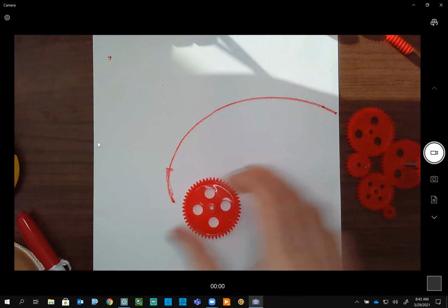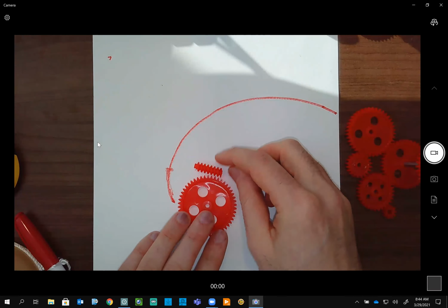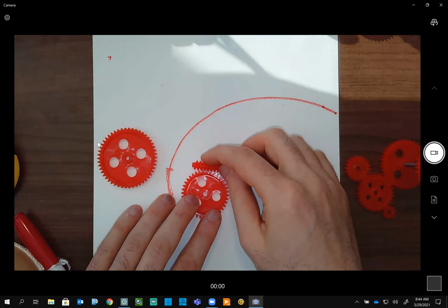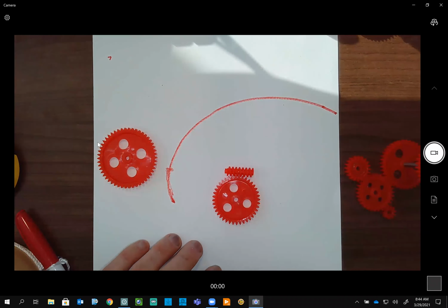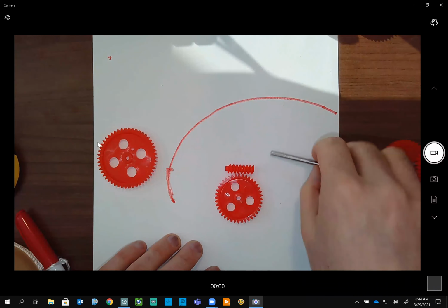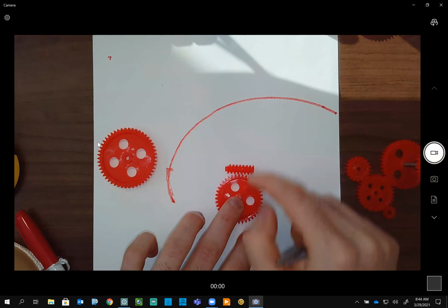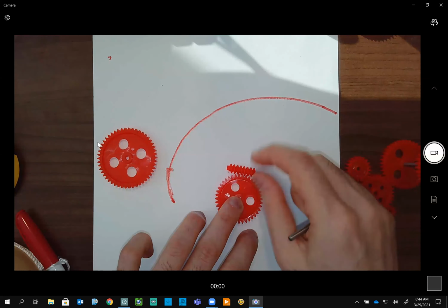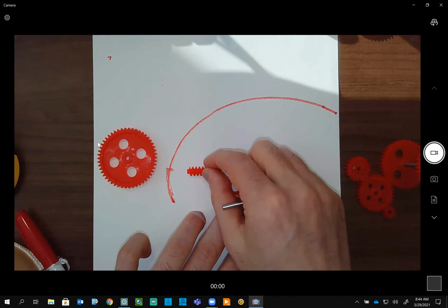Okay, it's here. I have one gear here, and this is, let's say, the worm. They mesh? No. These two mesh, yes. Something like that. All right. So imagine the axis for this one coming out of your screen, and the axis for this guy is here, like this shaft. So if this guy is fixed and I rotate it, it's more like a screw. Depending on whether it is right hand or left hand, it's just going to move, right? It's just going to move over here.